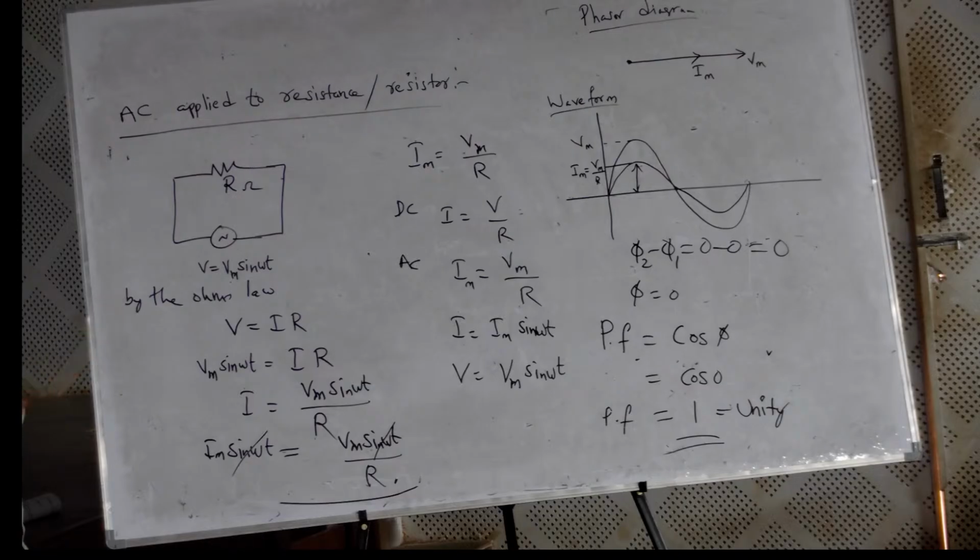Kindly remember the equations. V is equal to Vm sin omega t, I is equal to Im sin omega t, and Im is equal to Vm by R. What is the power factor of this circuit? What is the value of power factor? 1.